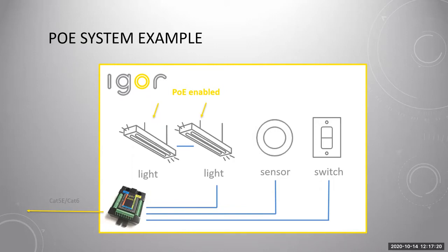And we've built into our software and our node programming a heartbeat that goes out to each of our emergency lighting nodes. If utility power to the building is lost, and thus any path in that heartbeat is severed or dropped, network or server wise, that heartbeat drops. And so our emergency nodes, within 5 seconds, will turn on their connected emergency lights at 100% or whatever the emergency dimming level is.